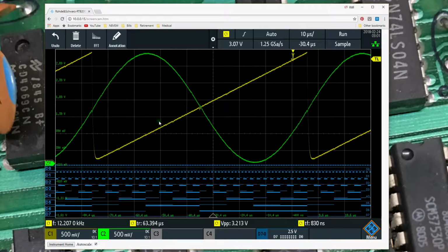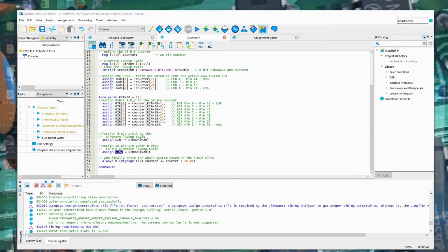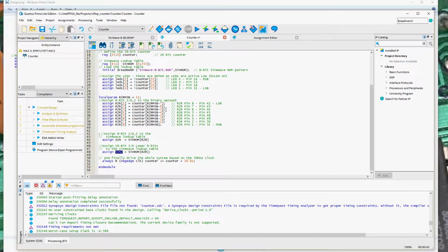Anyhow, that's really all there is to this. We saw the definitions before in the code, and I've captured it here, of creating the lookup ROM, loading the lookup ROM, wiring the lookup ROM to be connected to this up count. Anyhow, let's jump in and go ahead and change the bit that I'm connected to here. If we move the starting bit on the up counter to 12, we should double the frequency.